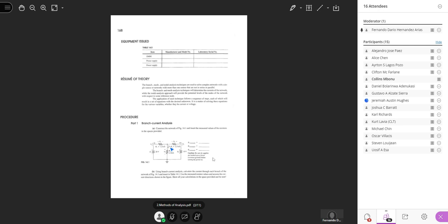So you have to get a third equation. To get the third equation, you will help yourself using Kirchhoff's current law, and you can do it in this node here. Every current coming into the node must leave the node, or the sum of all the currents entering a node is equal to the sum of the currents leaving the node.